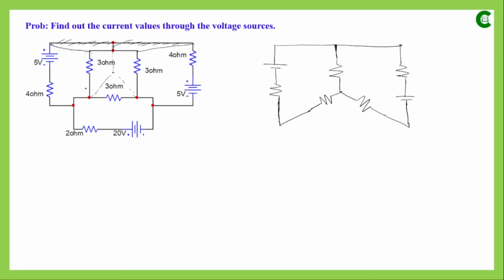So this part is over, this part is over, the equivalent star connection is over, and what is left is the bottommost branch, whose 2 components are connected between this point and this point. In our modified diagram, this is one point and this is another point. So we can connect this voltage source and this resistor along with this voltage source.